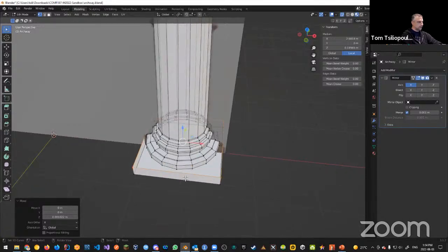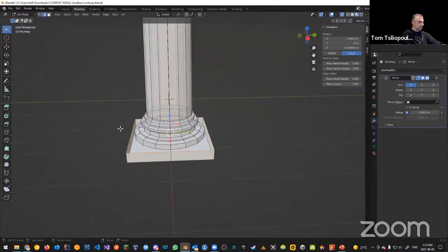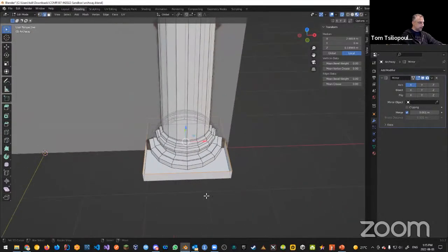So I look at each of the sides, right, each of the edges, and I want to break the edges up into something like 3 pieces. So if you look at that, and I've selected the top parts, I want to go now into edge select mode. I've selected the top edges, all these top edges, right?